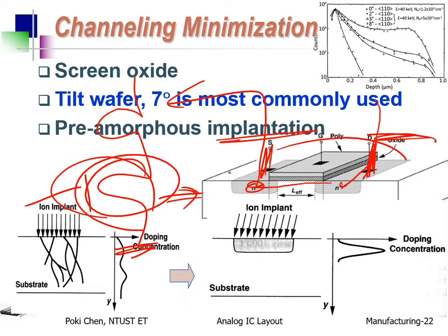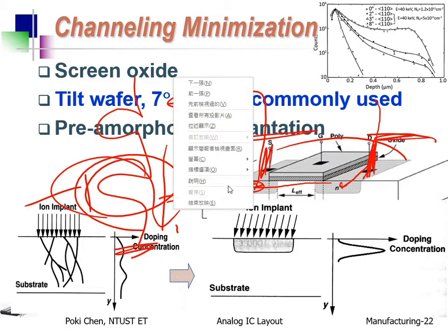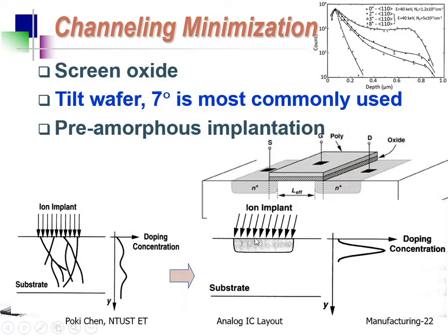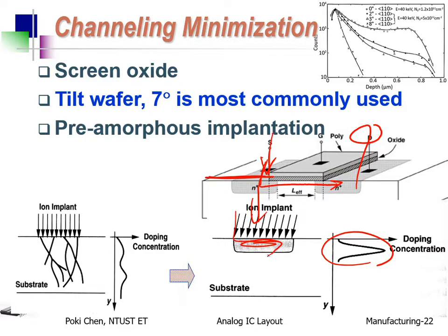The current flows from drain to source. But what is inside the drain and source? Actually, free electrons. Because they are majority carriers. 它们是主要载子. Okay, so it means what? The free electrons will go in this direction, then beneath the surface, all the way from source to drain, then to metal 1. Okay? So, the higher the concentration here, the better the conductivity for your free electrons.